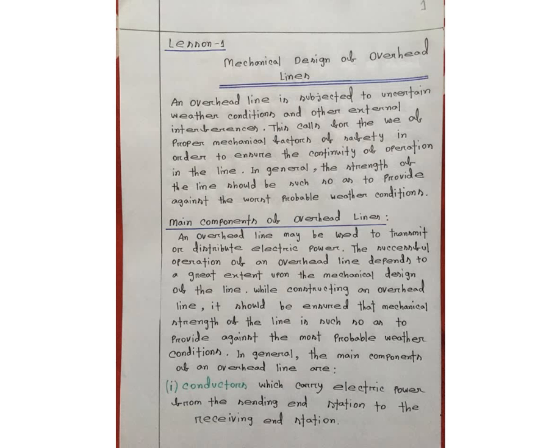An overhead line is subjected to uncertain weather conditions and external interferences. This calls for the use of a proper mechanical factor of safety. Many mechanical factors of safety have an effect on the overhead line. So in general, the strength of the line should be such as to provide against the worst probable weather